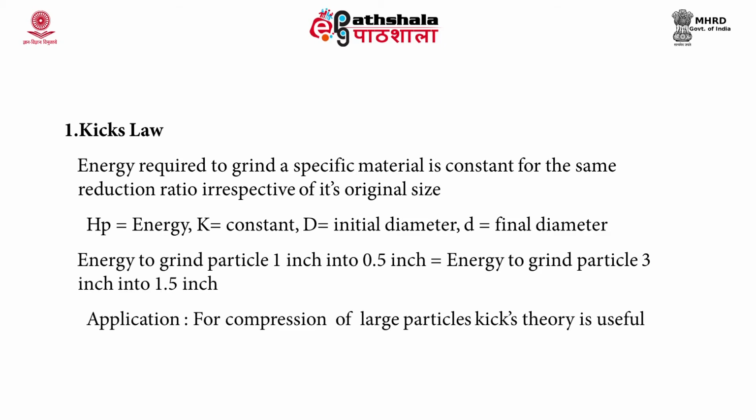Now, the energy to grind a particle of 1 inch size into 0.5 inch size will be equal to the energy to grind a particle of 3 inch size into 1.5 inch. If you substitute this in the formula, dividing 1 by 0.5 you get 2, similarly dividing 3 by 1.5 you get 2. The application of Kick's law is for compression of large particles.